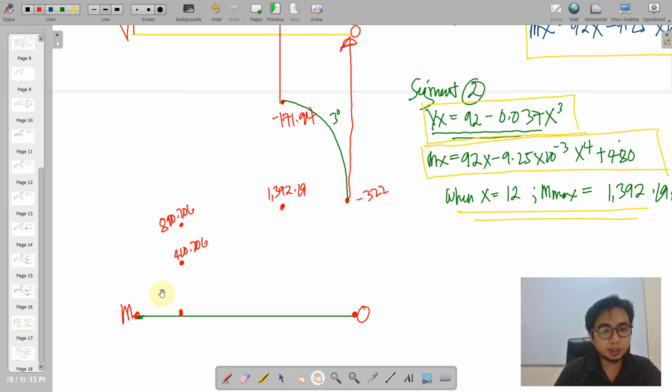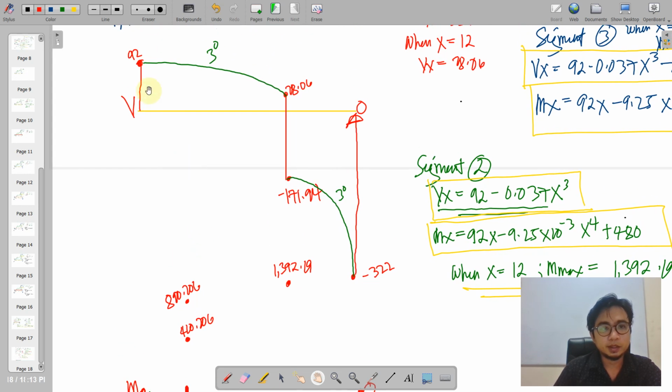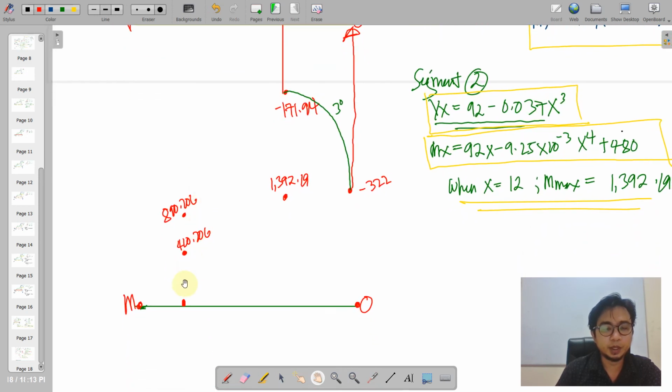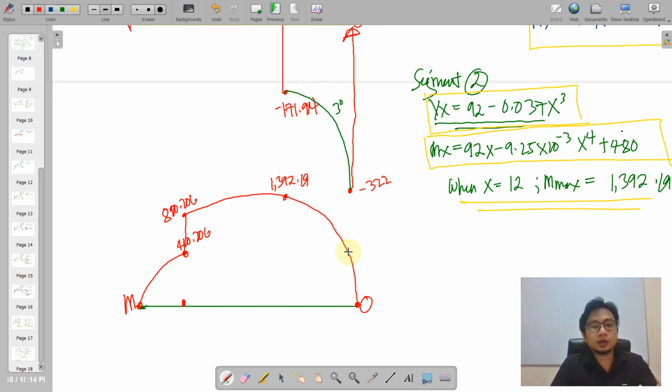So to connect these lines from 0 to 410, take note that we have here a decreasing curve, a decreasing manner. We have a concave downward connection. So here it is, and then an increase, just a straight line. So that your straight line is that one, and then of course the same concave downward curve to connect this. And then it will yield back to 0. So this will now be our moment diagram for this particular problem.